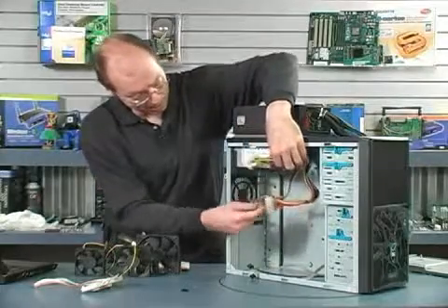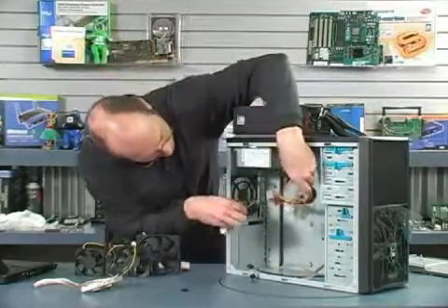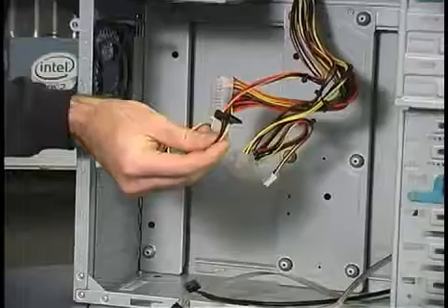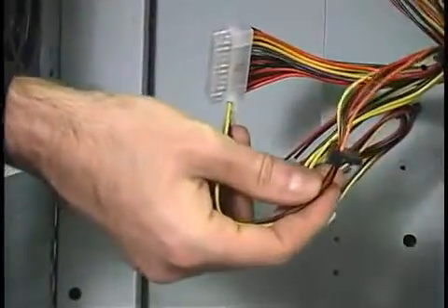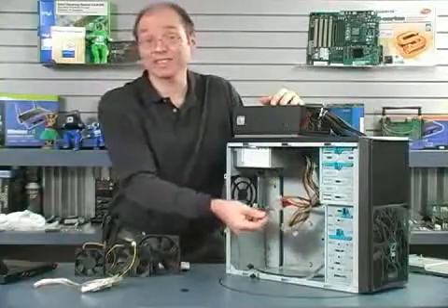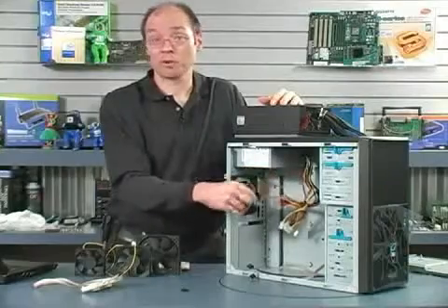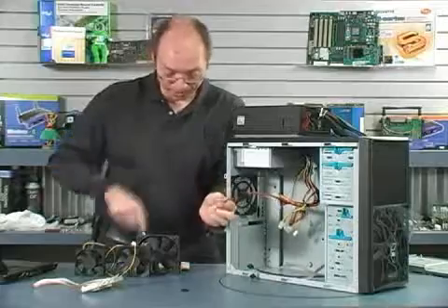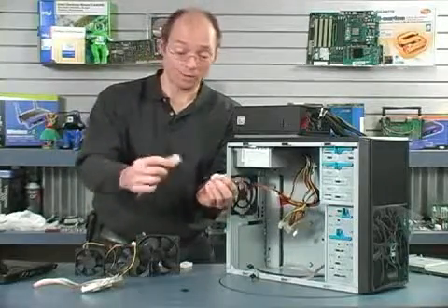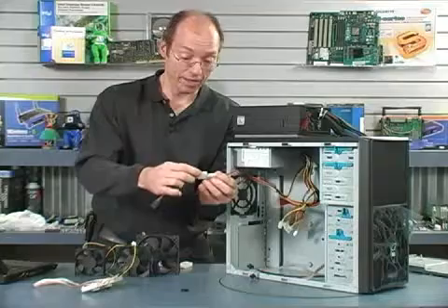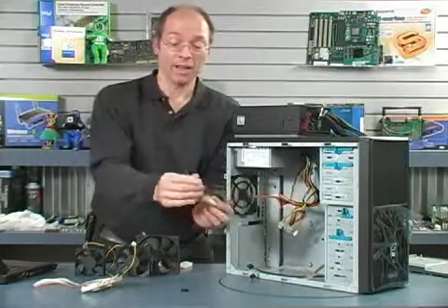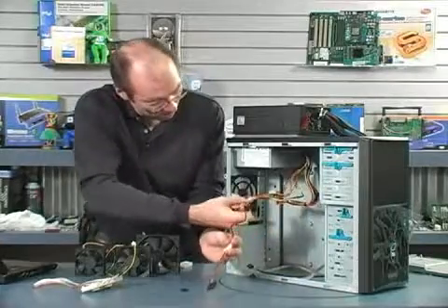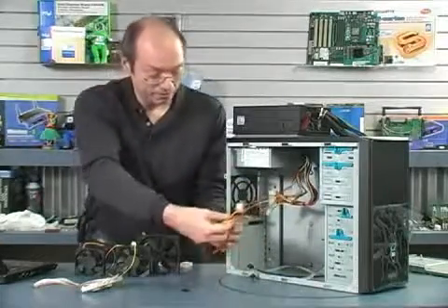This power supply that came with this case has literally one SATA serial ATA drive power connector. Now I plan on installing 4 hard drives in this case, and I could fit 6. I'm not going to be able to power 4 or 6 hard drives with a single connector like this. Now you can get adapters. Here, for example, I purchased what's called a Molex to serial ATA power adapter, and I can plug that in, and now I have another serial ATA power connector. I guess I could get a couple more and use these, but we simply don't have enough drive connectors, period.